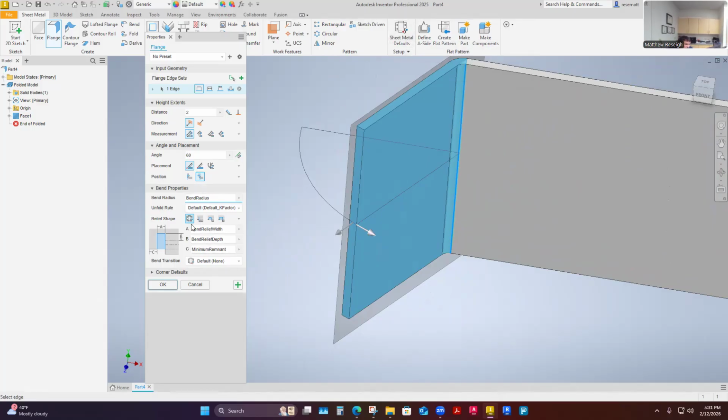But I can override that by saying, actually, I just want that to tear. This kind of shows that if I'm bending some area, but I'm not bending across here, then I'm going to do no relief and just let the machine bend through here or tear through it. There still might be a relief cut in here, but it's maybe not going to be this big rectangular cut. It might just be a real narrow slit that allows that to bend, but not bend right here.